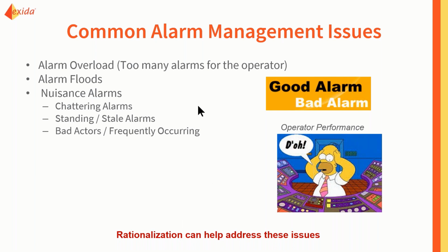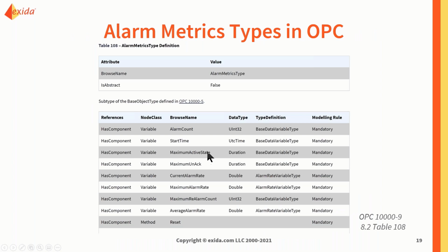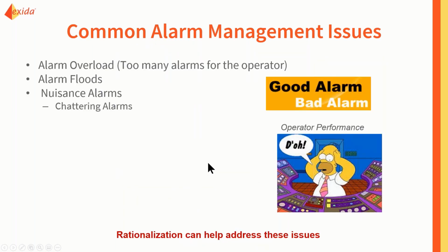Another thing that's very important when it comes to alarm management is the problem of standing alarms. As I mentioned, it is related to the metrics, such as the maximum active alarms: the alarm just stands there and there's nothing that you do. It can be there for several days or 7 weeks. I've seen alarms standing there for 2 whole years, and no one did anything about it.